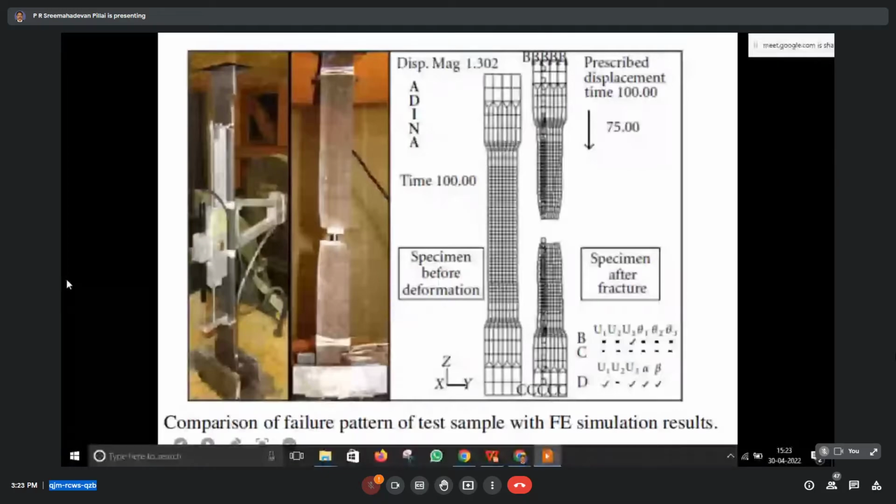And this is actually the finite element modeling of the stress. This test, you would have done in your lab. This test is called the tension test. Tension test you do in the lab with the help of a UTM. When the tension test is done, with the help of extensometers and strain gauges, we can plot this diagram. This is the FEM simulation of the stress formation here.